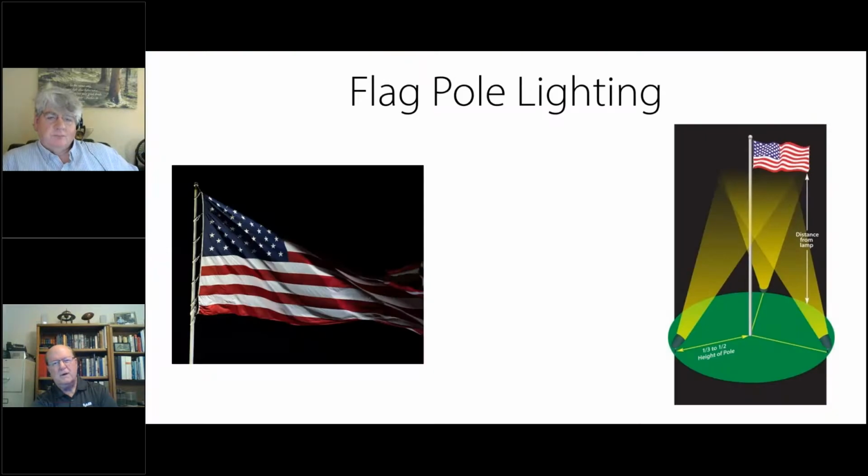Okay, so I'm going to turn it. We'll continue on with flagpole lighting. So flagpole is interesting. The rule of thumb is 3 fixtures is really the best, in a circle of 120 degrees from each other all the way around, like we see in the diagram.